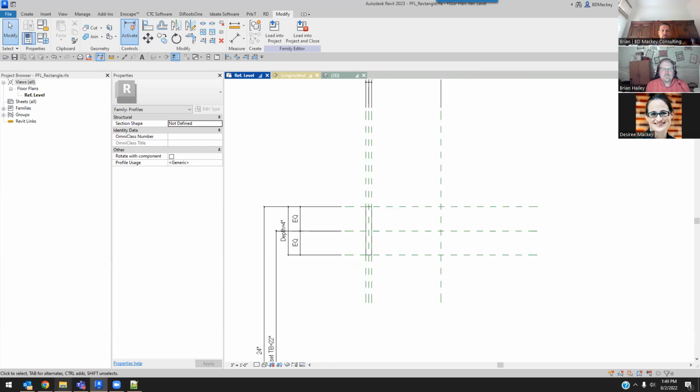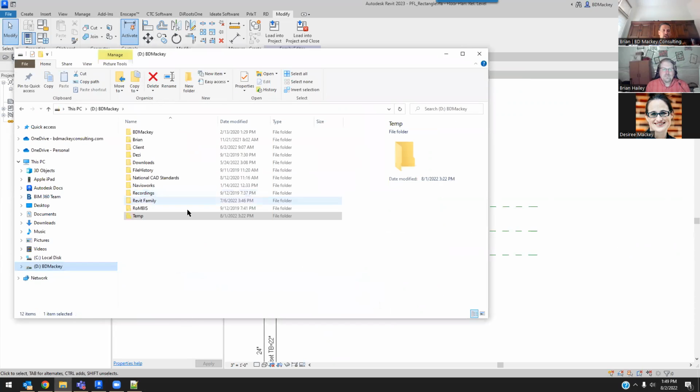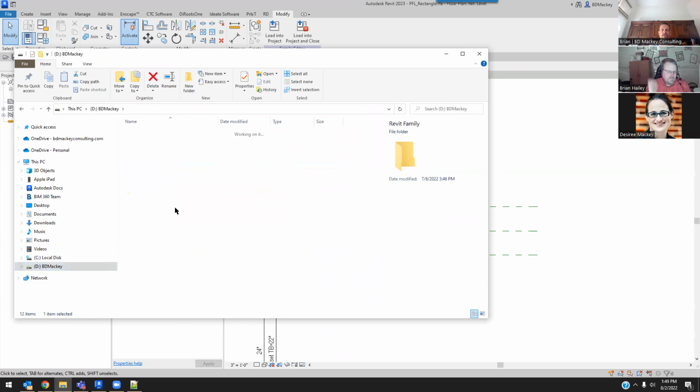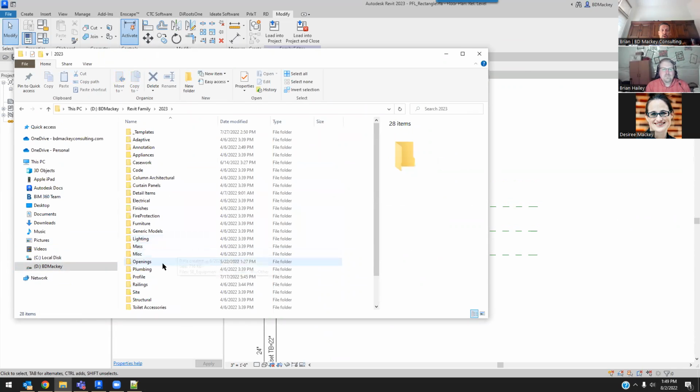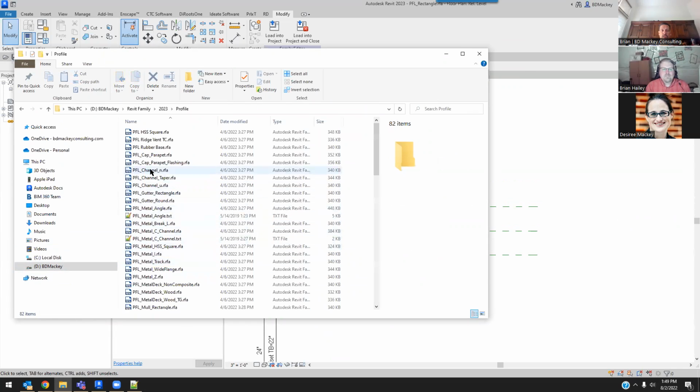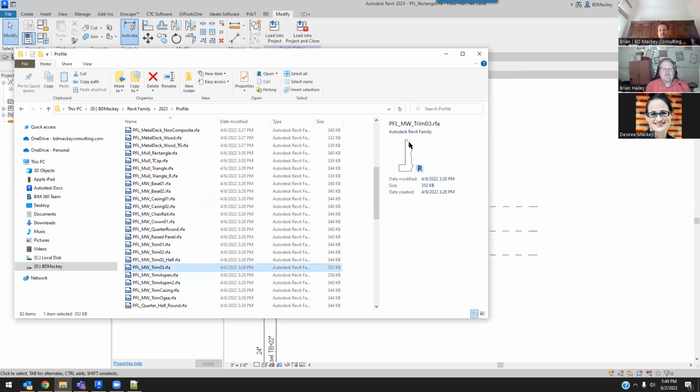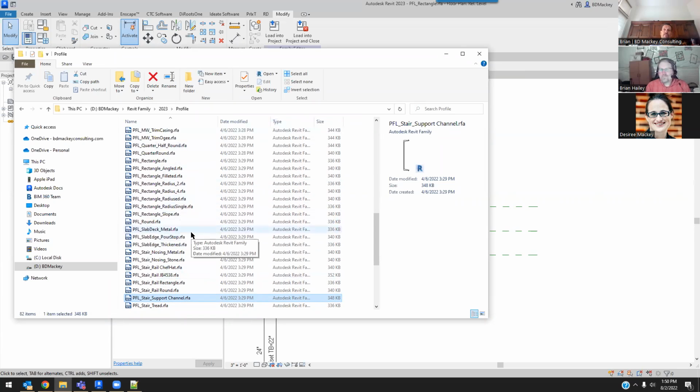And if I actually go look at those, you'll see that I have a ton of those in my Revit families. Like every single one of my families, for the most part, profile families, has that option. If I come look here, like this U channel, I can do the same thing. The metal eye, it's got the same thing going through here. So any one of these, maybe not some of these trim ones. I created these quite a few years ago and I haven't updated them, but the majority of these I have are going to be, hey, yeah, I want to be able to offset and move this. So I used to create like rectangle TL, rectangle TR, that'll be top left, top right kind of scenario as we went through.